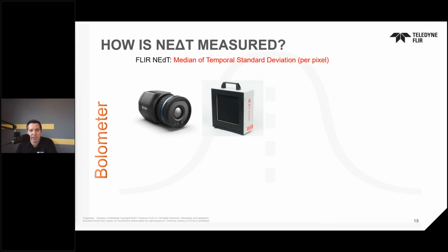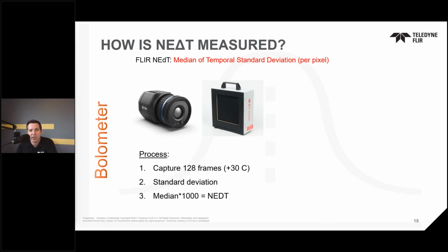So for bolometer type detectors, we see a less rigorous measurement process. And again, that's due to the trade-off in design of bolometer versus cooled photon counter. The bolometer is optimized for the highest performance that can be reached at the lowest possible cost. So there's a large amount of signal processing that occurs at the detector hardware level itself. Because of all that signal processing, access to low-level data and controls is pretty rare. Also, due to the bolometer design, there's no customizable integration time.